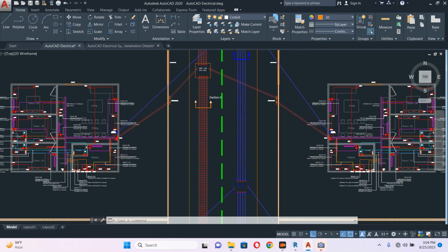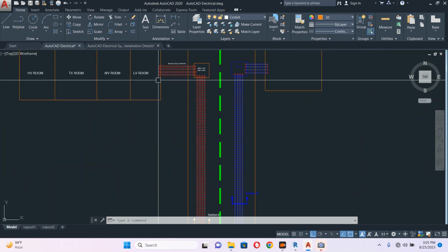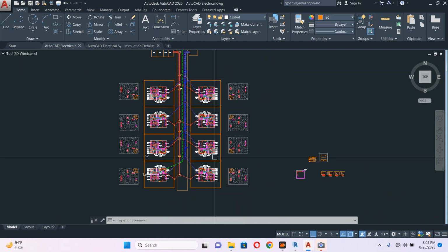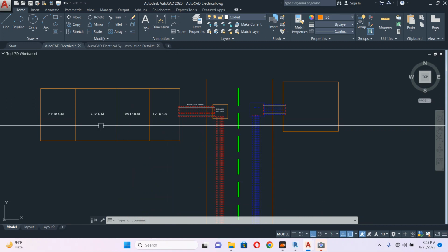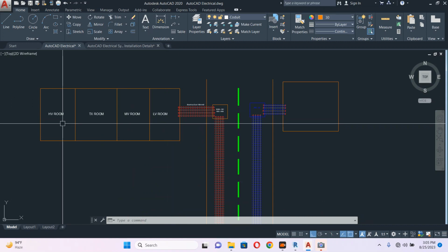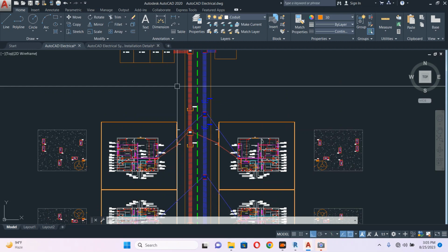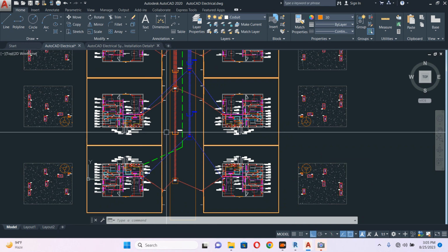And calculate how to calculate the cables. From here I want to tell you how to check SMDBs. So I will make this one SMDB, this one SMDB. From there I will go to the MV, from there to the transformer, then to the HV. So let's play with the generator power also. Then we will know mostly 60 to 70% of how to make an electrical power drawing.